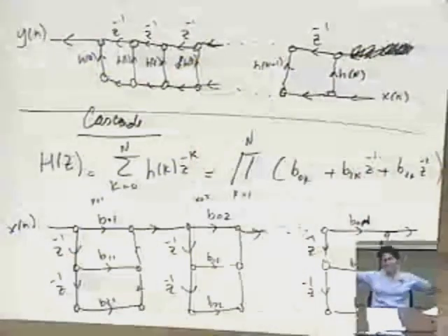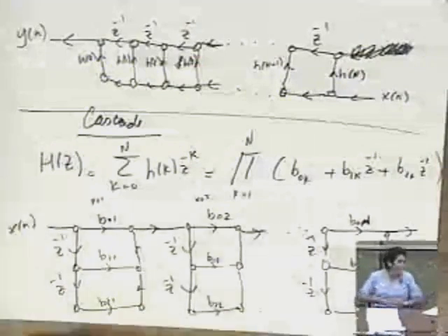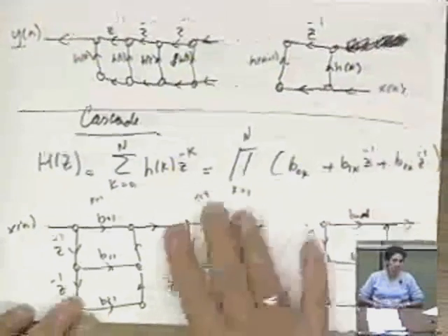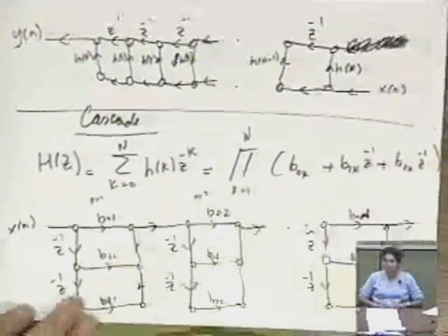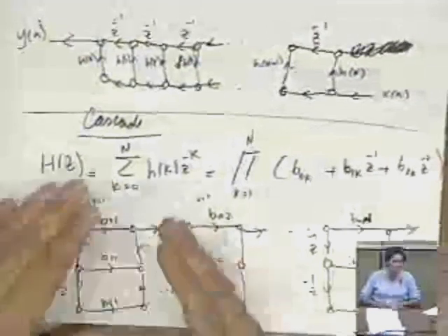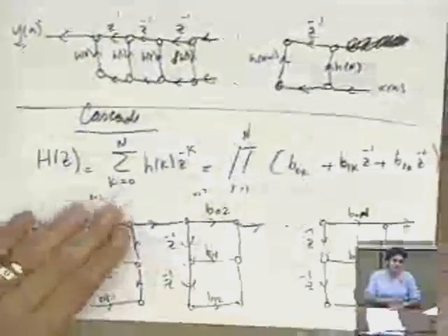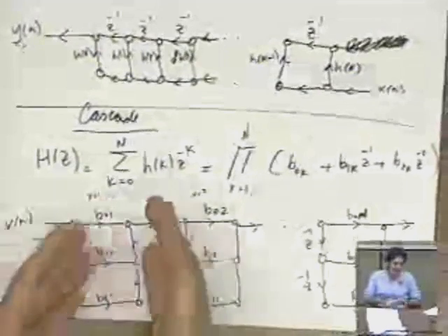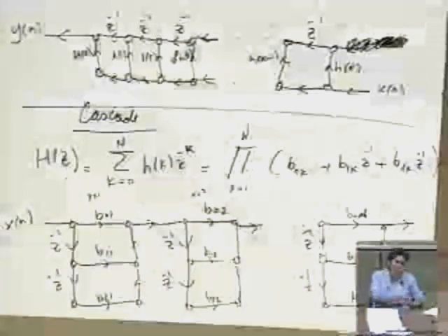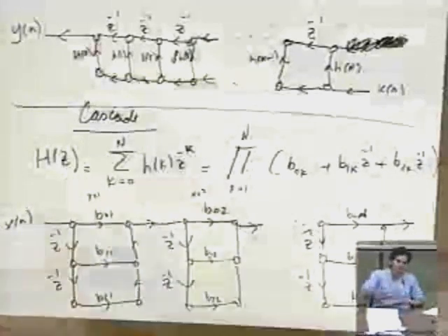The finite word length effects are still important to study because on your cell phone, we're not carrying an Athlon with 64 bits. That's just not a portable device. On your cell phone, probably everything is implemented in 8 bits or at most 16 bits arithmetic. So it's still very important to worry about these effects, because once you quantize things and do the round-off, even though you designed the filter properly and under perfect implementation conditions it would work, in reality you've implemented a different filter.